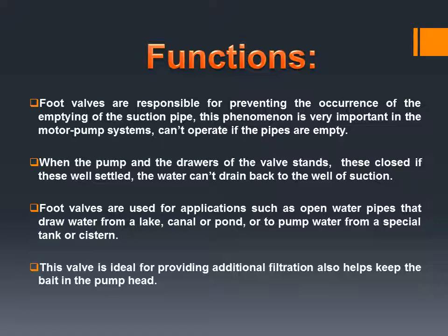Foot valves are used for applications such as open water pipes that draw water from a lake, canal, or pump, or to pump water from special tanks or cisterns. This valve is ideal for providing additional filtration, and also helps keep the prime in the pump head.